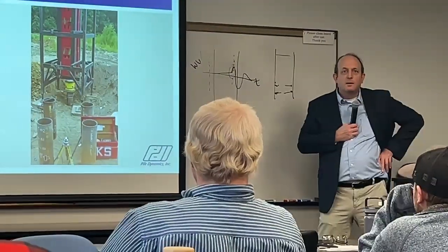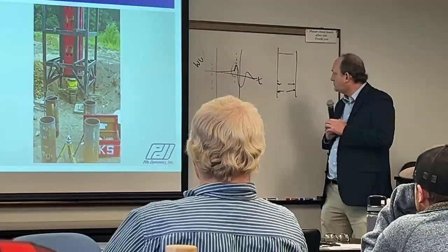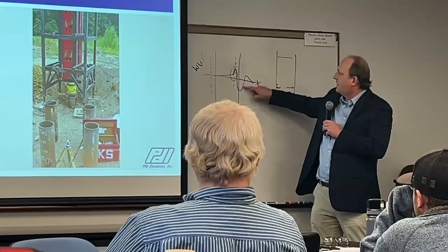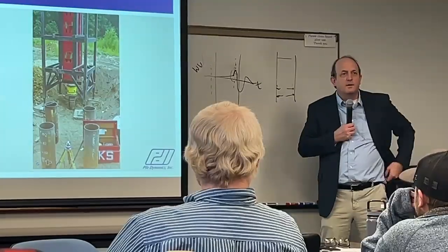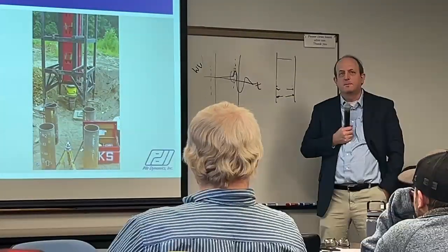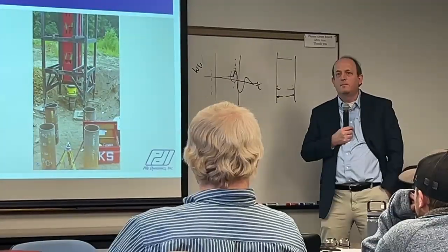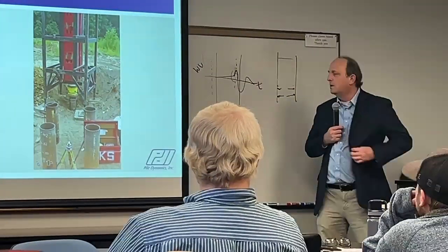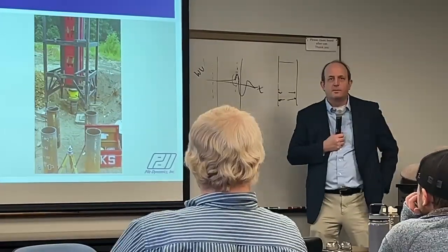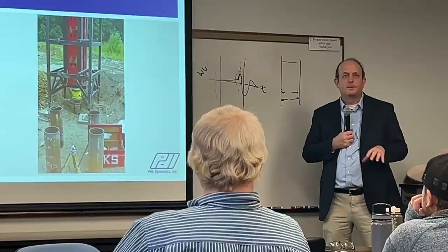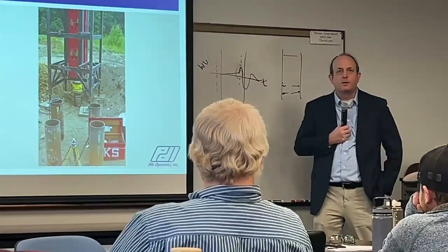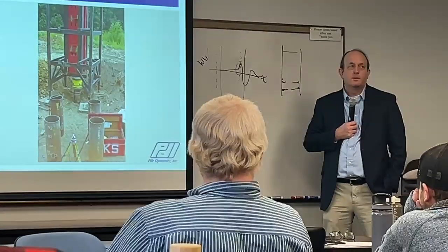And so that's part of it. What happens out on the end bearing and how one models that in signal matching is also something that gets debated a fair bit. And we'll often do that with an extension of the CAPWAP model called radiation damping, that lets some of the soil around the outside move a bit as well, either whether it's in the plug or whether it's outside of it.